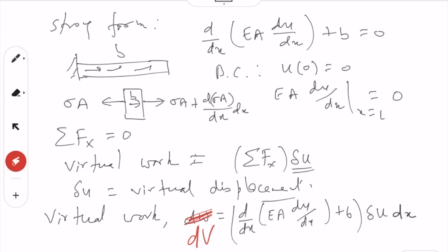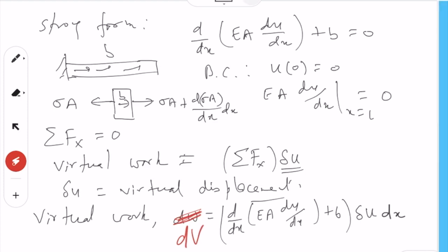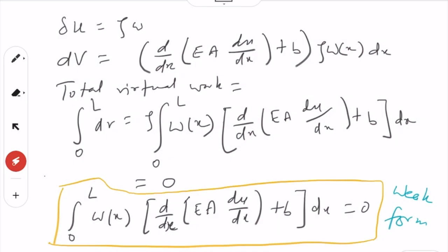In this case, we start from the strong form, and then we have applied the physics, or the solid mechanics basically, and in this case also we are getting the weak form. So basically the idea was to show that there is a physical meaning of the weak form, and it simply tells you this is the virtual work. It tells you that virtual work has to be equal to 0. This is what it tells you.